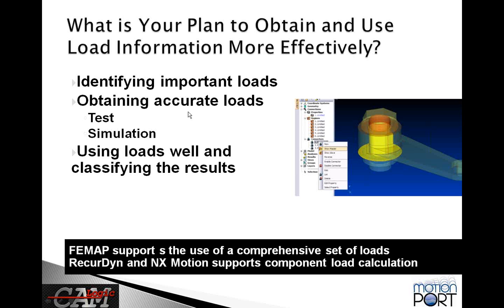And then once you obtain those accurate loads, it's a matter of using these loads well in FEMAP, making sure that you're defining loads using best practices so that the loads are being distributed properly through the structure.